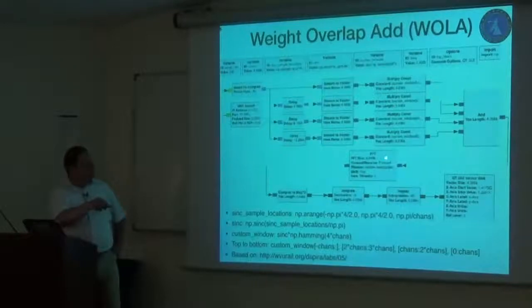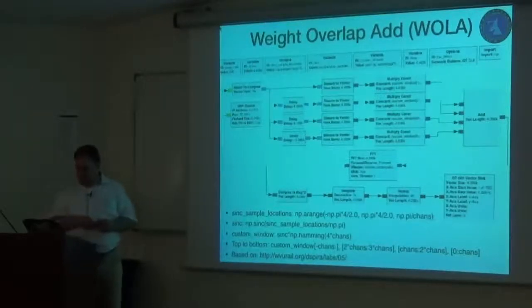And then there's a big missing line here. They go into the FFT block, and they go over here. And then you again do the complex to magnitude squared to do a power measurement, to integrate the whole thing, repeat the thing again, so that you actually have a live display, and you put it in the Qt vector sink again.